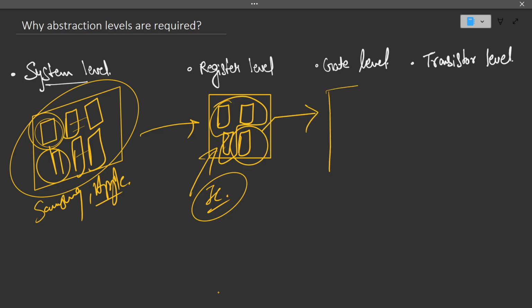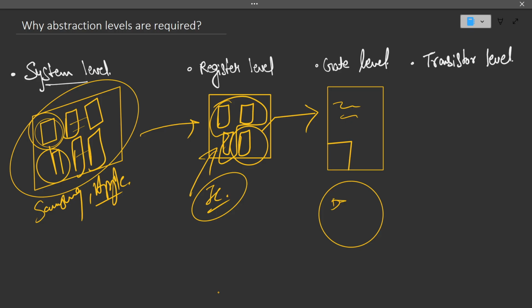For example, the EDA tool companies are simulating the design, they are synthesizing the design. So based on some code they are changing it into gate level. When we are changing it into the gate level, they need the information about how this code should be converted into gate level. So that's why they needed this gate level abstraction.